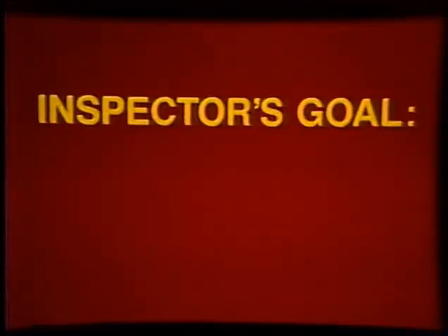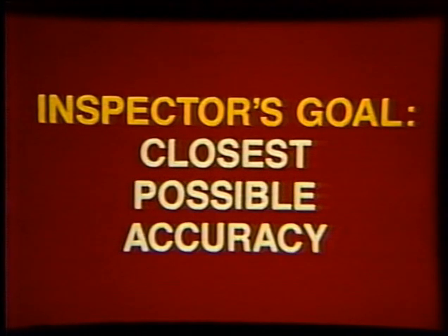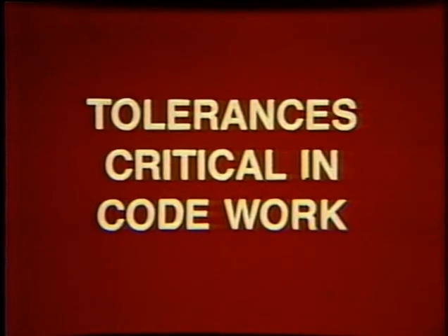In general, the inspector's goal should be to ensure the closest possible accuracy to the details of the weldment specifications. As the work becomes more critical, the attention to detail becomes more vital, and very tight tolerances are required in critical or code work because of the necessity for high strength in load conditions of heat, pressure, or stress. Welding inspectors must be aware that welders who consider themselves craftsmen always strive to produce sound welds with good appearance.